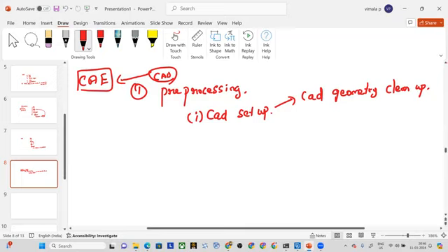and then do the next procedures to find out the simulation and find out the output parameters. First, what you have to do is remove certain unwanted features which are given for aesthetic purposes, which are not at all going to be in the technical consideration. Those things have to be removed first. So that is called CAD geometry cleanup, which we'll see in detail while we load some components in the ANSA software. I'll show you. So this step is very crucial, and this is the first primary step under pre-processing. Okay, so you can also call this model geometry cleanup. Okay, remove the unwanted features.